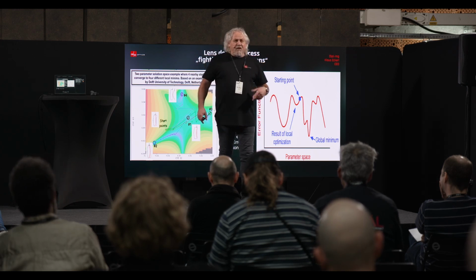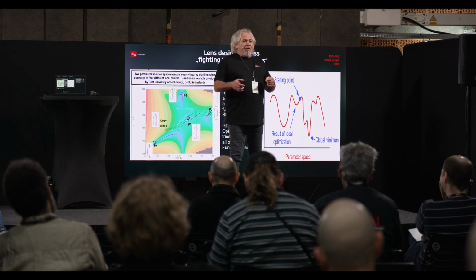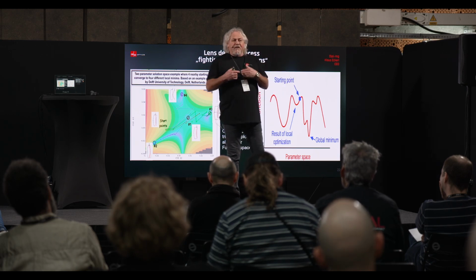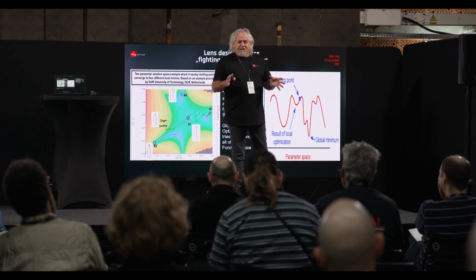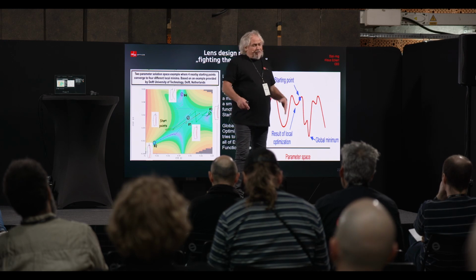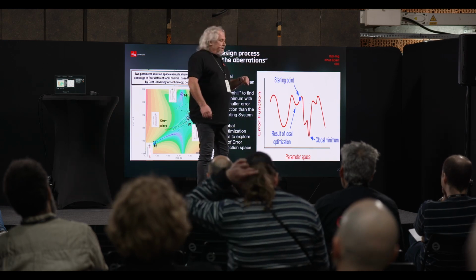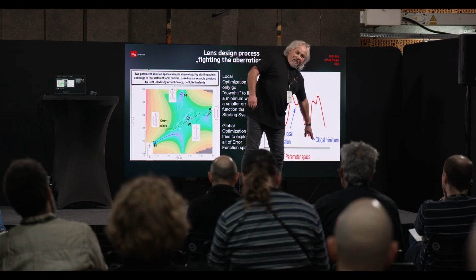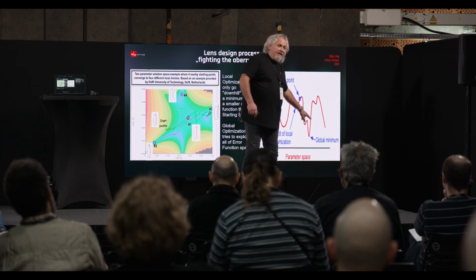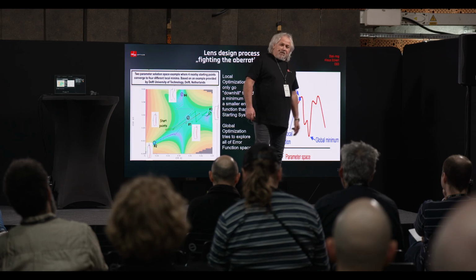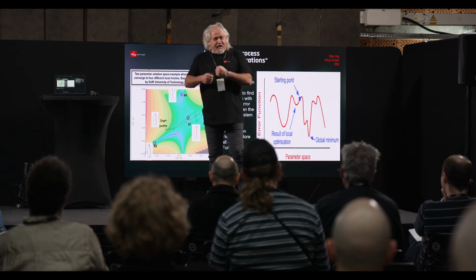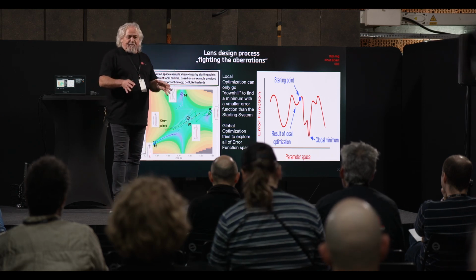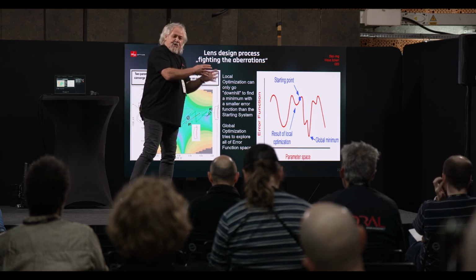And that's a real big problem with the algorithms in optical design. So if you're a very experienced optical designer, you take this and put it somewhere else because you know out of experience that you have to go into this region to get this design done. And there is a newer structure, existing for years now, called global optimization. It means the algorithm really forces the system to climb over the hill and look whether there is a deeper valley after that. And even if it found that, it climbs another hill to see whether there's another deeper valley. So it's a rather time-consuming ray tracing process, trying to find regions that are better. If you're experienced, you can speed that process up enormously, because you put them in the right region.